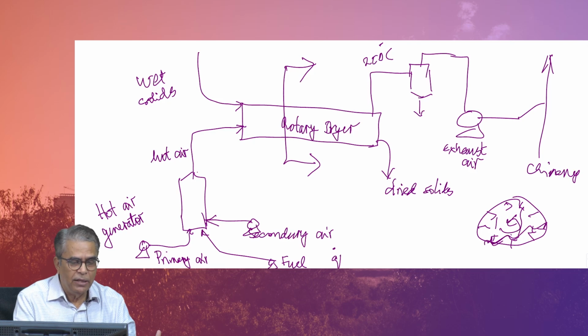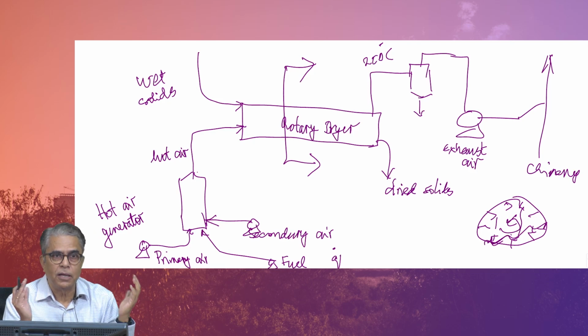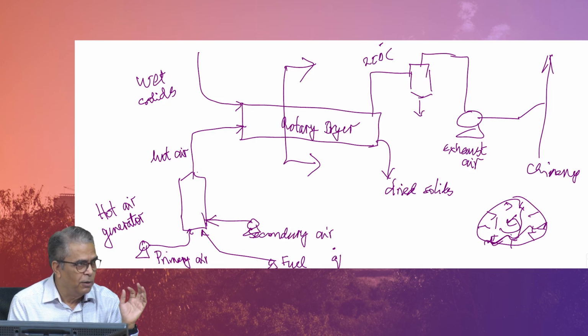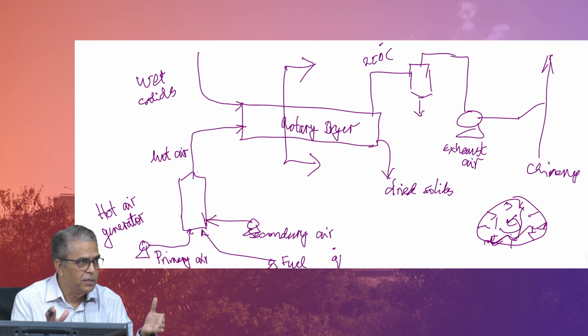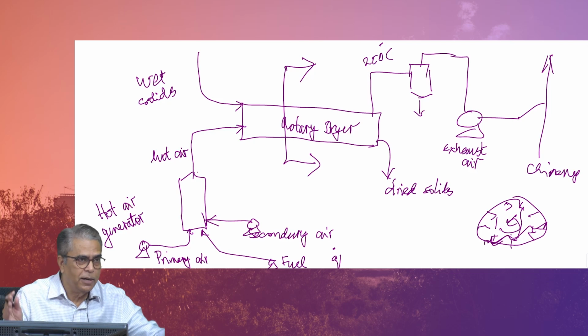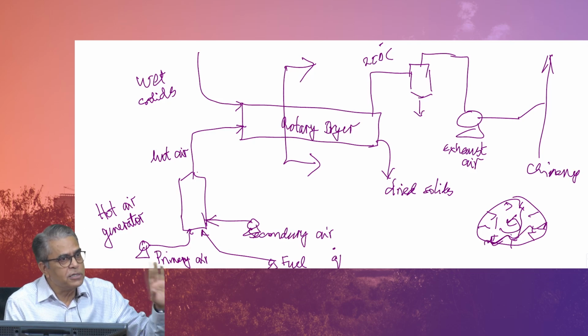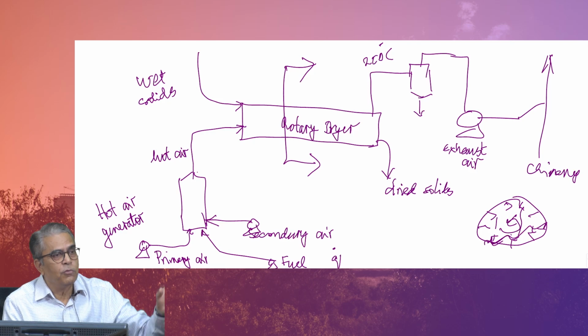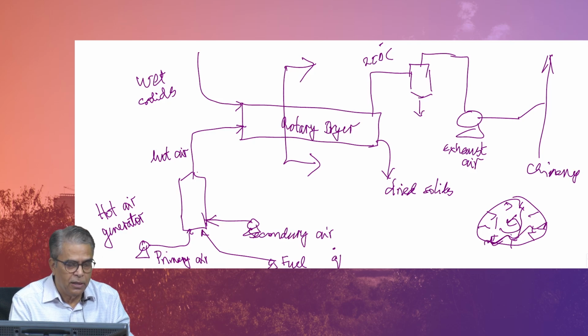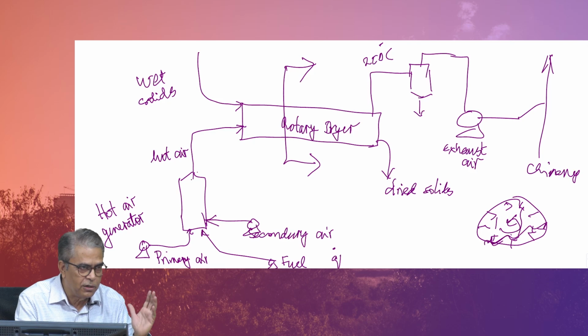Now, handling that air and putting it into the dryer is a disaster, because it is at a very high temperature. Even the furnace, if you go through the next step, you will find has to be nicely insulated inside to protect the metal wall. Metals lose their strength at high temperature. So, the furnace is made out of some physical element, some steel plate, and internally it has insulation material and all that. This hot air will still be very hot, and the quantity of air, if you have calculated it, will be moderate, it will not be very high.